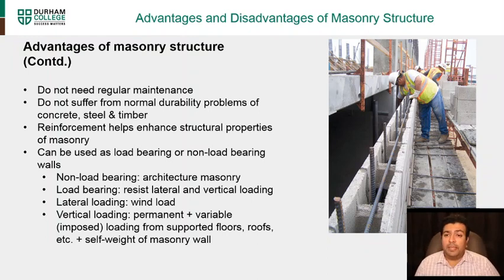Reinforcement helps enhance structural properties of masonry, so you can have reinforced rebar used to reinforce the masonry. It can be used as load-bearing or non-load-bearing walls. Non-load-bearing walls is basically for architectural masonry. Load-bearing is to resist the vertical and lateral loading. Lateral loading is also the wind loading, and vertical loading is from permanent structures like roofs that are put on top, or slabs that are floors that support the floor.